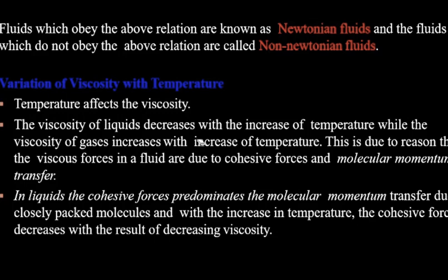Temperature will definitely affect the viscosity because temperature acts upon the molecules and how the matter is packed. In gases, the molecules move randomly. In liquids, the effect is somewhat less compared to gas. The viscosity of a liquid decreases with the increase of temperature, while the viscosity of gases increases with increase of temperature.